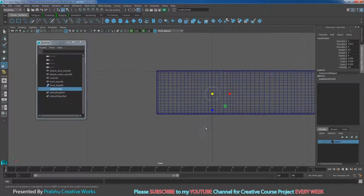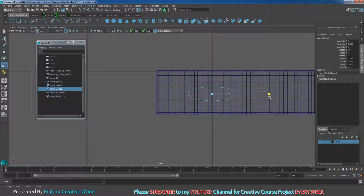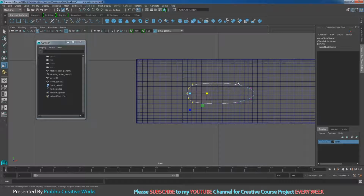So right click and choose control vertex. Before that I will scale in X. So right click and choose control vertex. I will select this control vertex. You want to scale in X, don't keep it straight, you want to keep a little bit of round shape. So you want to select this control vertex, you want to select like this.